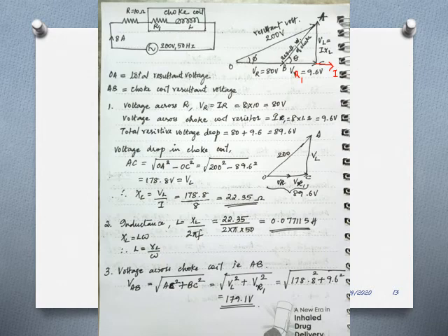So you have two sides of the triangle, BC and AC. BC is the voltage across R1 and AC is the voltage across L. So using the triangle law, you can find the resultant voltage of this choke coil by completing this right angle triangle. So the resultant vector will be AB, that is the voltage across the choke coil alone, which is making an angle theta with VR1.